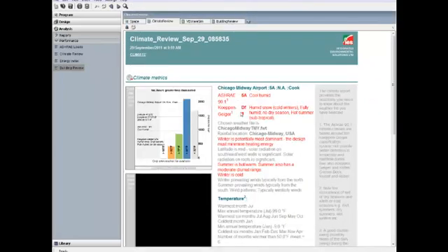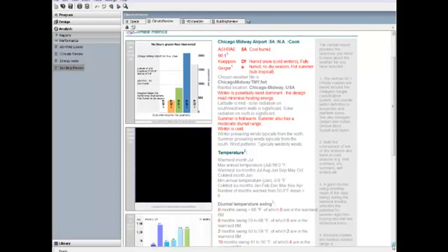This analysis helps you to understand the climate for which you are designing: information about what direction the wind blows, the coldest and warmest months of the year, and other general weather data. The results of this analysis can be used to drive decisions on things like the type of construction materials that you want to use. It can actually be run with just longitude and latitude to get a quick idea of the environment before finalizing the program.